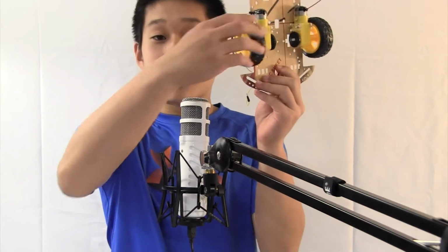But in order to make our car even work, we need the bulk of it, the chassis. Now, you can get any tank with 2 motors that have positive and negative leads, and make sure they accept 9 volts. And make sure they don't draw too much power, because then we're going to burn out our motor driver. These small yellow motors, like these, they work really well. And then we need a 9-volt battery right here, and a holder so that we can plug it into our circuit.